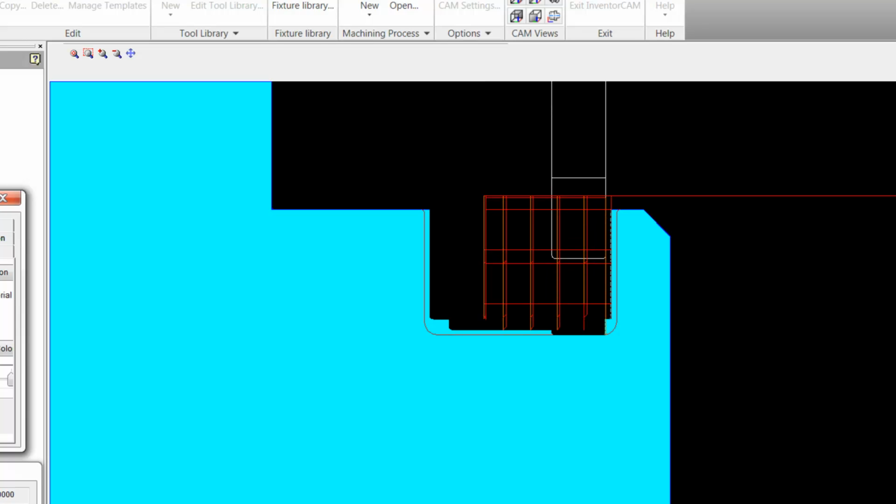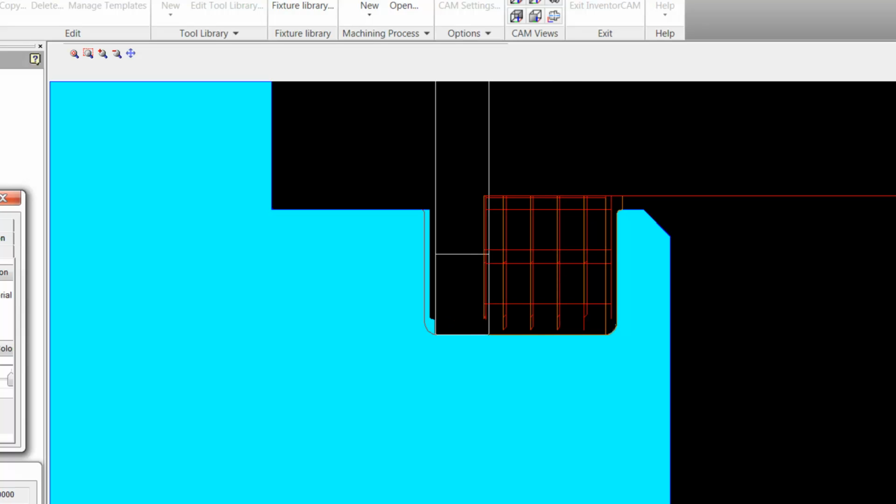The finish, it'll go down, then back up, get the corner, get that bottom corner, and now it'll move across on the bottom. That's what the advanced keep down does. Now it'll move back up, go back to the side, finish off that edge over there towards the bottom, and now work its way out of the groove.